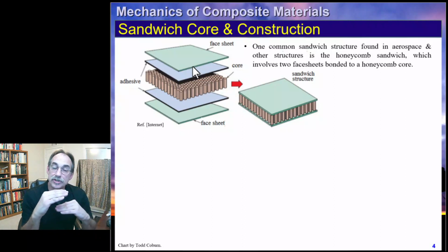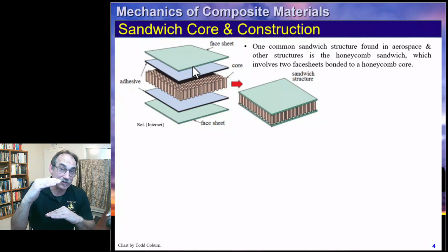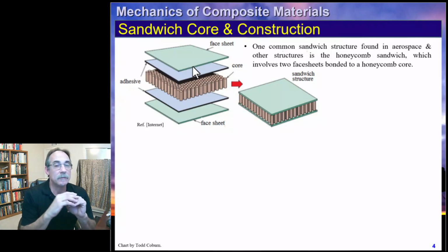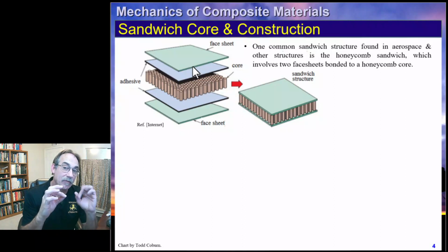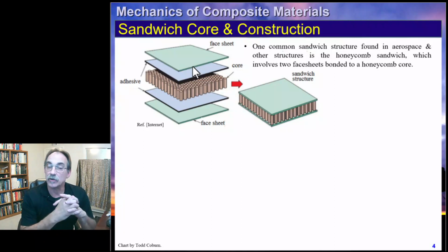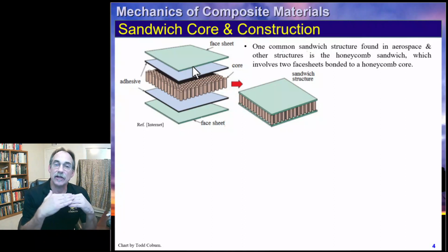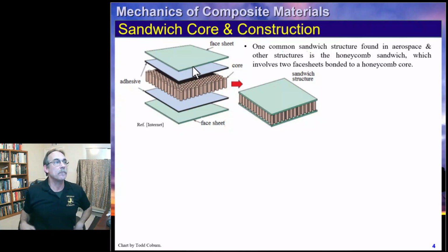What we'll do is just push those face sheets further apart with more thickness of core to get a more efficient structure. But if we have somebody walking on it, or there are point loads applied to the surface, then we're going to need to thicken up that face sheet, or both face sheets, in order to withstand those, so that load can distribute to that soft core.